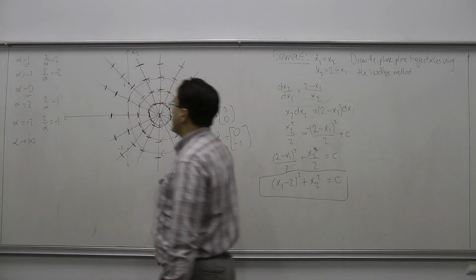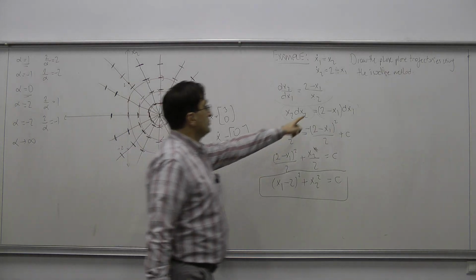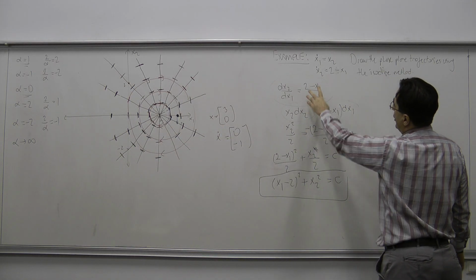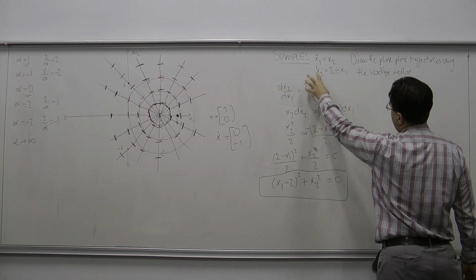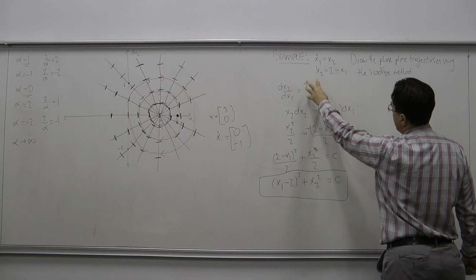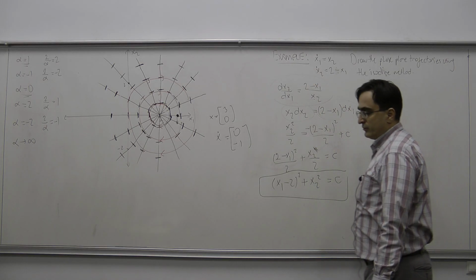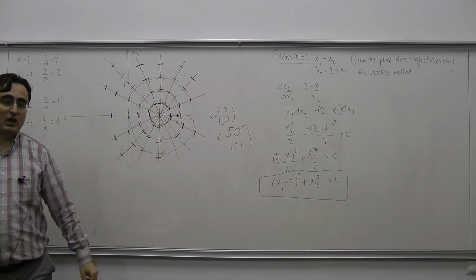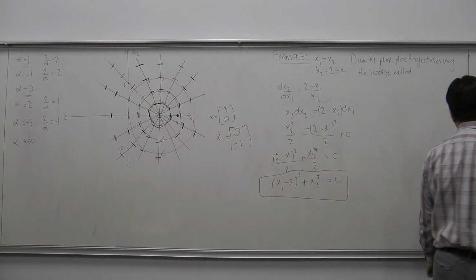Similarly, in the isocline method, after you select your alpha, if you equate this to alpha, you need to be able to draw the curves that would result from that equation. Okay? And in this case, those equations gave us some lines which were easy to draw. Similarly, in order to be able to apply the isocline method, those curves should be easy to draw.